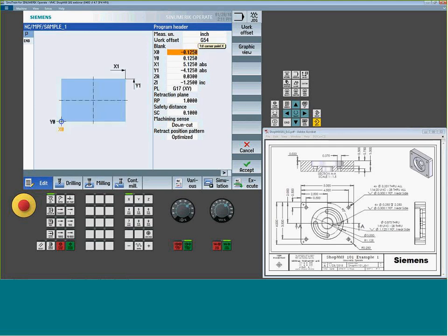When I'm setting up the model, I'm just telling it two opposing corners. Either one, in my case, I'm using the upper left-hand corner and the lower right, or I could use the lower left, upper right. It doesn't matter, or go backwards. So I'm telling it that I'm going to have an 1/8 inch of stock on one side, because remember, we're going to finish at 5 inch. So my stock would be overall a 5 1/4. So I want to take half of that material, or an 1/8.